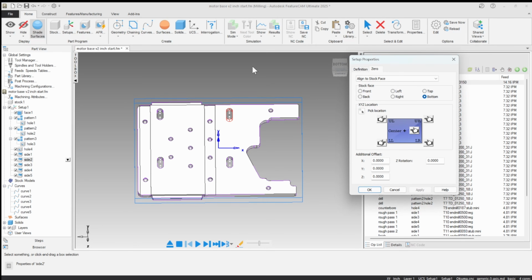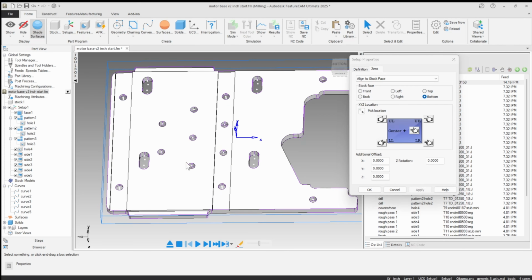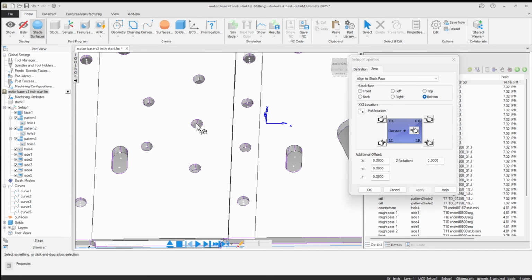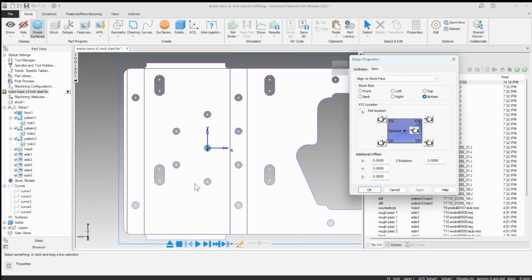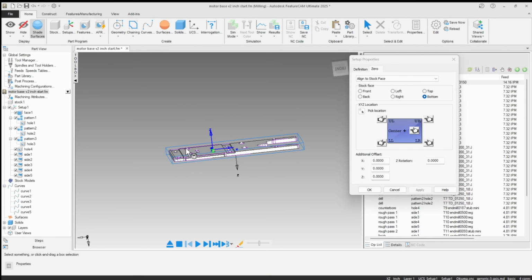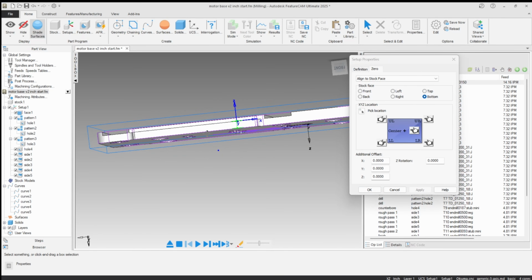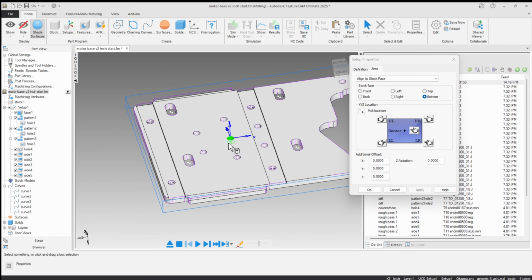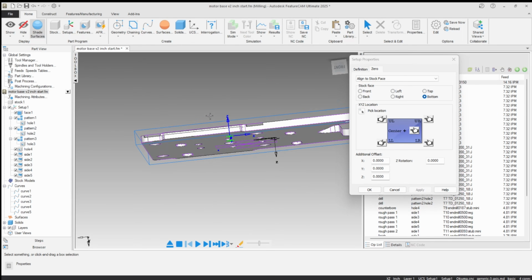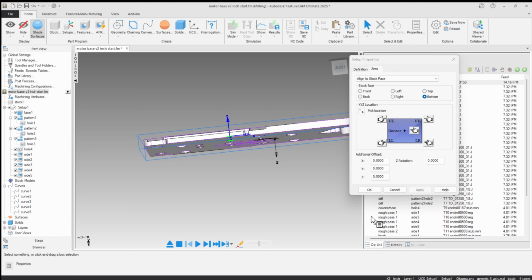I can even place it right in the middle, or I could place it over something that I already have, right? So let's say, just as an example, I want to put 0 over this hole in the center of this bolt hole. I can do that by hitting the pick location and snapping onto the cylinder center. And if I go here and look, we'll see we're right down on the model and centered over the hole. So I just need to make sure that hole's drilled through deep enough because I have material I have to face off, right?